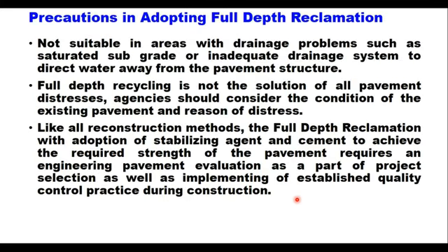There are certain precautions to be adopted in case of full depth reclamation. It is not suitable in areas with drainage problems such as saturated subgrade or inadequate drainage system to direct water away from the pavement structure. Full depth recycling is not the solution of all pavement distresses. Agencies should consider the condition of the existing pavement and reason for distress.